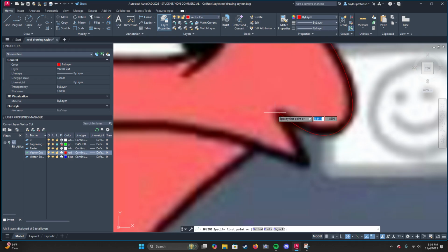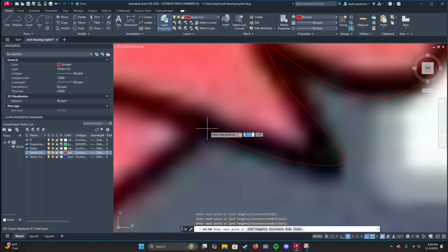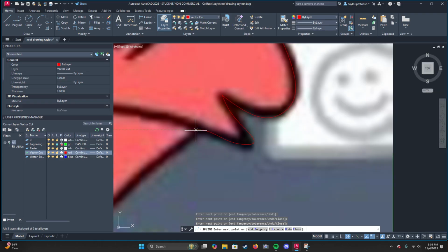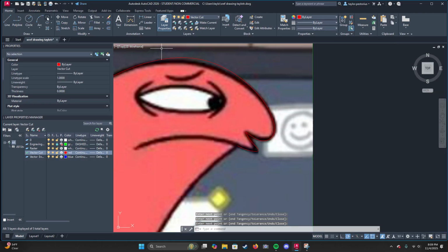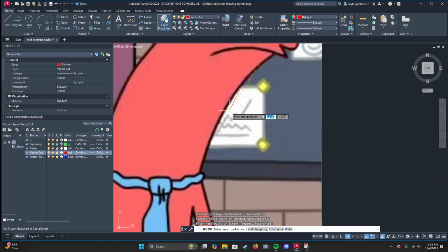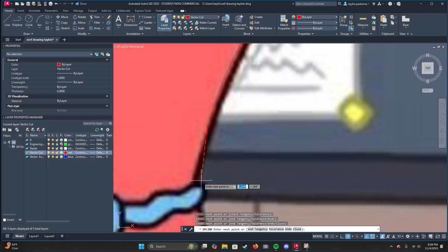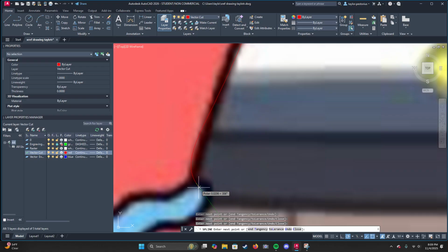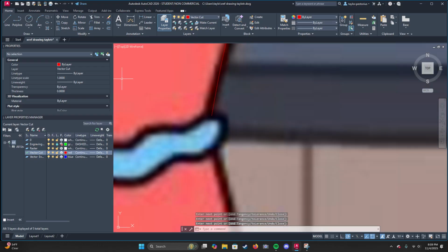Again, I'm going to my spline. There it is. And I am currently just doing the outline. And I'm doing my outline in red. I'm hitting the space bar to go again. I'm just doing my red outline. This is going to be my cutout line. Now, once I do my whole outline in red, I'm going to start the engraving portion in blue on the inside.